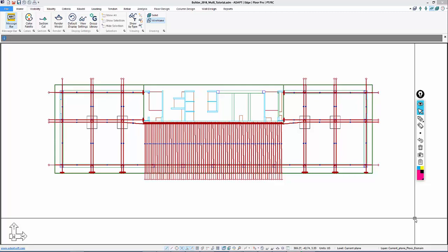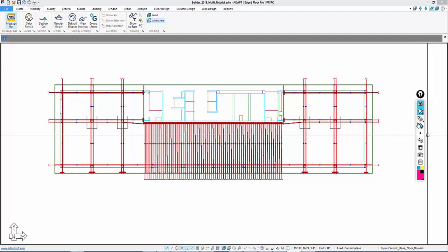In this segment, we're going to take a look at results along strips relative to the post-tensioning that we have modeled in the slab. And one item that we didn't do in the last segment, but I'll bring it up here, is we may wish to add some PT along these two edges, so we have some continuity and pre-compression along that edge, and instead of having just this hard line of tendons being stressed in this direction, where we have this corner, we could develop cracking here.